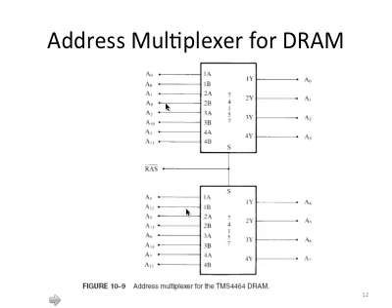So what we're seeing here is we are using this row address strobe to connect to the control bit for this multiplexer. Based on the value of row address strobe, one of the two channels will be outputting.